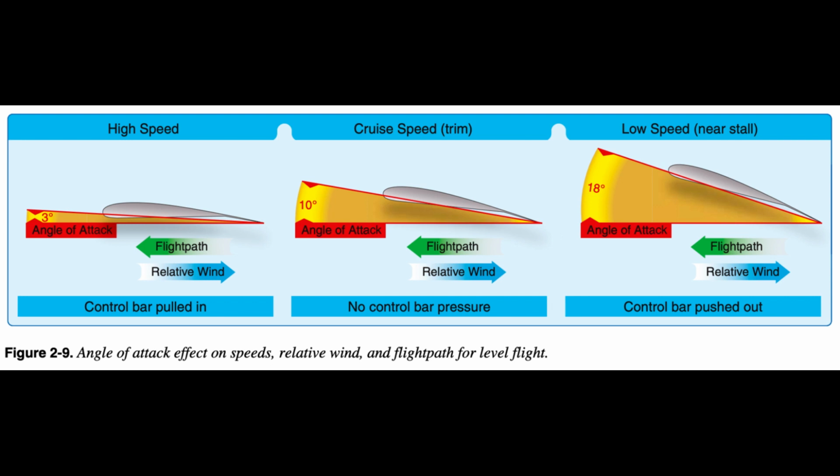Planform is the shape or form of a wing as viewed from above. The WSC wing comes in a number of planforms ranging from the larger and slower wings to the smaller and faster wings. Aspect ratio is the wingspan divided by the average chord line. A WSC aircraft with a common 200 square foot training wing, about a 35-foot wingspan, and with a typical mean chord line of 7 feet, would have an average aspect ratio of 5.